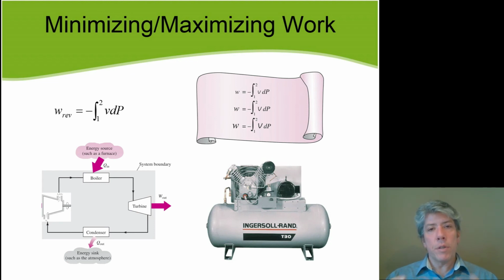So we could either choose to throw away the energy while we're compressing it so that it requires less work to compress. And so, yeah, sure, we don't put quite as much energy in the fluid or the air, because some of the energy left as heat. But it won't require as much work. We don't have to put as much work into the fluid in the first place if we cool it during compression rather than cooling it while it's in the tank.